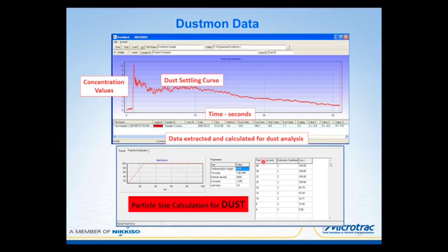And over here you'll see that the particle sizes, in this case from 45 microns on down, are provided as cumulative percent smaller than data. In this case it's showing that 100% of the dust is smaller than 25 microns. But very important to us is that 32% of the dust is less than 10 microns, and definitely within the respirable region of the dust sizes.